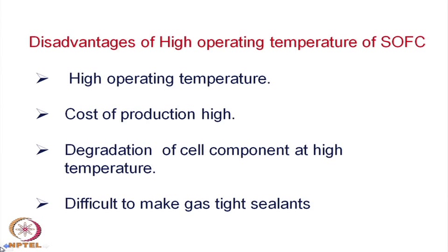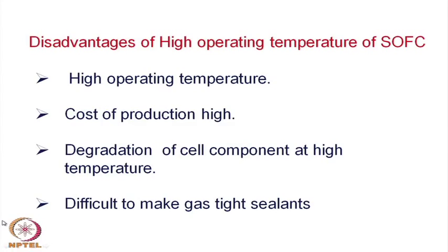Because we are talking about 2 different gases, and we do not want the 2 gases to combine or come in contact with each other except in the desired way. The desired way is the electrochemical combustion, but otherwise they should not come in contact with each other, and therefore, we need to separate out the 2 compartments, and that is a very challenging task for any fuel cell developer.